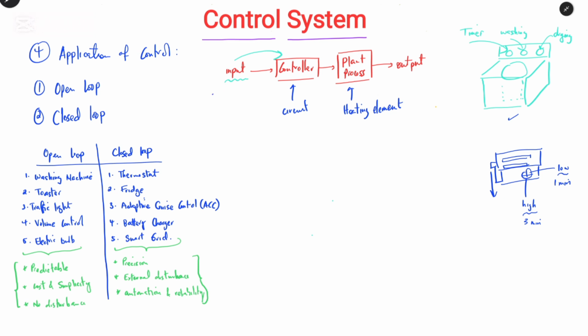Therefore the input we can say is the knob, which represents either a high or low selection, and the other one is the press. When we press the switch, it will start the toasting process. We can simply look at the schematic. We have, for example, the switch. When the switch is pressed, it is connected to, say, a 555 timer.